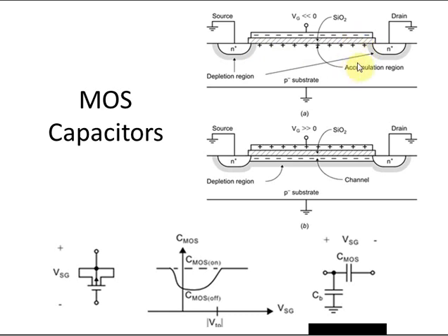Over those moderate source gate voltages, you have a much lower value of capacitance. So you have a tuning curve for this varactor that looks like this. Its capacitance varies as a function of the terminal voltages in this way. Now the model for this device, again a two-terminal device, looks something like this.